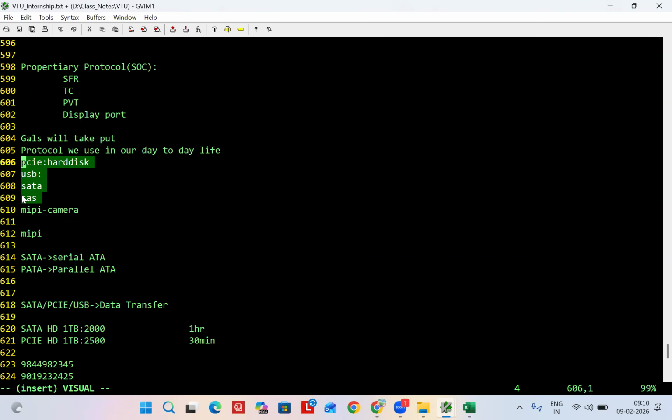2 seconds, you can understand, right? It's just one blink of your eye, and you can do a 1 TB data transfer. The speed is given in gigabits per lane, and we have 32 lanes. The highest transfer per lane here is 20 Gbps, and we have 32 lanes. 32 times 20 Gbps is around 640 Gbps. 1 TB is around 1000 something GB. So 640 in one second, and one more 640 in the next second.